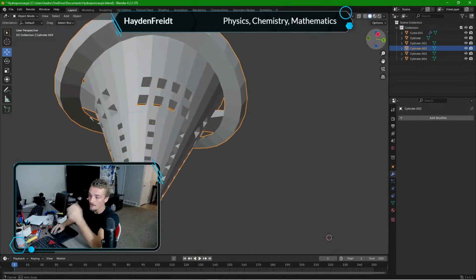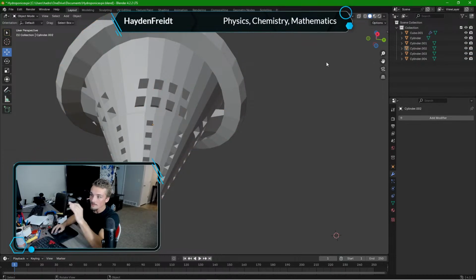Perhaps I'll have to put some netting down or something, because the one thing that I have yet to do is figure out dimensions and having them transfer properly. So when I build something or design something in Blender and I transfer it into my slicer software for my 3D printer, it never renders as the correct size. It never renders in the correct dimensions in which I began to design it in Blender. It's always way smaller. And so for whatever reason, the file just doesn't keep its size, it doesn't keep its quality. For whatever reason, it's diminished.